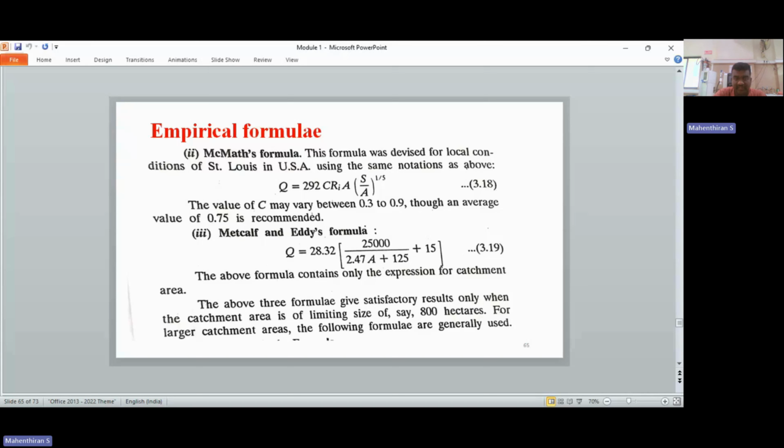By excluding rainfall intensity, the formula implicitly assumes the same design storm for all catchments. By excluding the slope, it assumes all catchments have similar topography. By excluding the surface coefficient C, it assumes all surfaces have similar imperviousness. Therefore, Metcalf and Eddy's formula should be used only where the project conditions closely match the original study conditions.